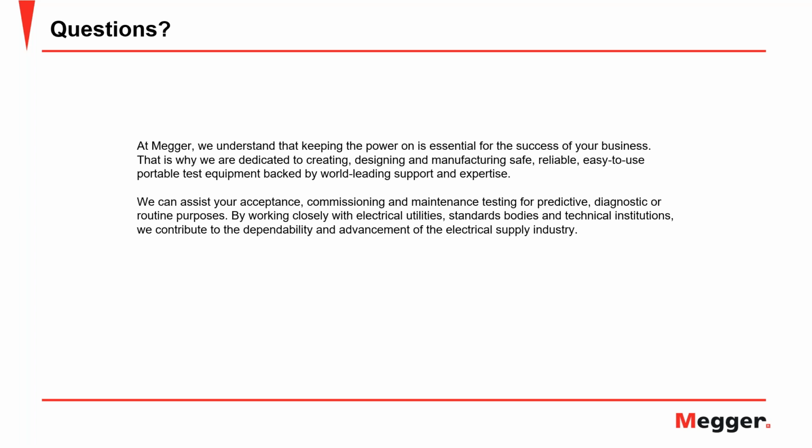Concerning the test further damaging the transformer insulation, no. Typically, this test will not damage the insulation unless you are applying a voltage that is higher than what the windings are rated for. You always want to look at the transformer nameplate, and if you enter the transformer nameplate voltages into PowerDB, we actually calculate what the test voltage should be to prevent you from damaging the transformer. But on larger power distribution transformers, if you're applying 10 kV and the winding is rated for 160 kV or higher, no, you're not going to damage that transformer winding.